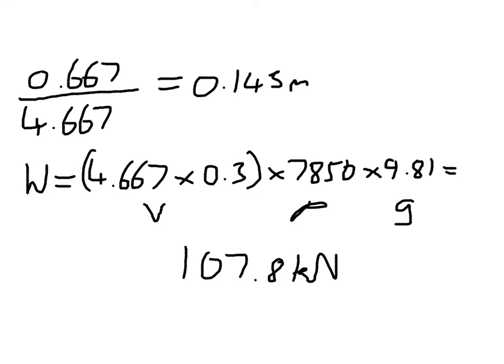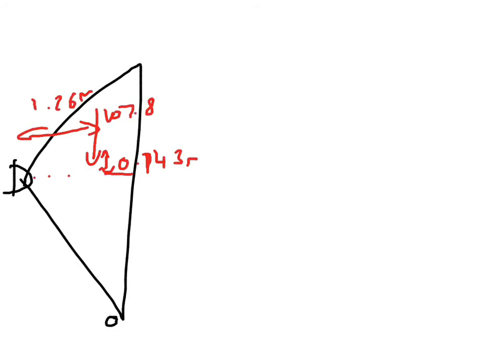We can then look back at our diagram. I'm going to quickly sketch it again. So that's a very quick sketch of our diagram. There are three forces that we don't know. This pin joint here will have an X and a Y force associated with it, AX and AY, and the B joint down at the bottom will have a reaction force associated with it. There'll be nothing in the slope parallel to the y equals minus x slope, because it's a rolling joint.